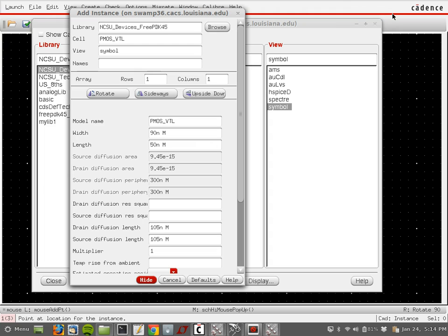What is the minimum size we can use here? For example, we can use 22 nanometer. No, the length you cannot change. You have to leave it. If you want to change anything, you would change the width. Okay, wait, so we can use 22 for example? No, what is displayed here is the minimum value of the width. Yeah. So if you want, you would increase it to as much as you want, but this 90 is the minimum. Yeah.